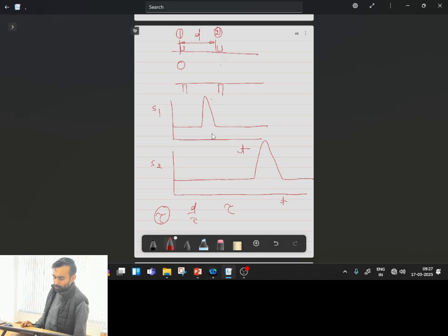So if the signal is sometimes positive and sometimes negative, it gives some challenges. But if the nature of the signal is similar, for example the presence of a bubble gives either a positive peak or a negative peak at all the locations, then even if both quantities are negative, their product will become positive. So this works in scenarios where your system generates the signal with the same sign upon the presence of the fluid particle. Is this one clear?